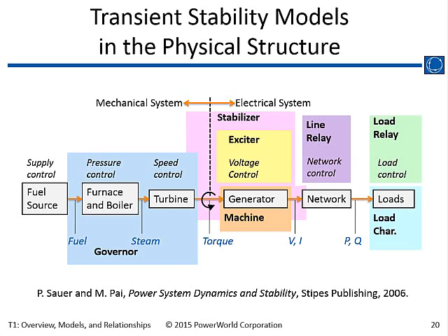The way these components are broken down is we use 4 principal models for an electric machine or generator. We call one the machine model, which models the dynamics of the physical spinning machine itself. Then there's a model called the exciter, which models the voltage control system.